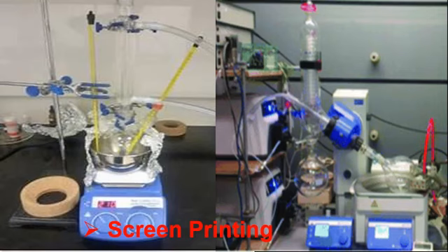Due to this, the structure of the material is damaged, and there is also a possibility of contamination being transported from the substrate into the deposited thin film layer. So although the chemical solution deposition technique is much less expensive, at an advanced level molecular beam epitaxy is more advantageous than the chemical solution deposition technique.